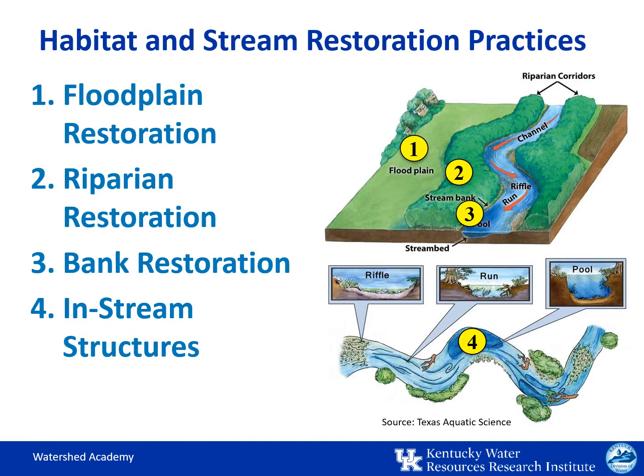Habitat enhancements frequently accompany stream restoration practices. Although individual habitat enhancements, such as boulder placement or felled trees, can be placed in the stream, the best approach to improve habitat is to restore a fully functional, well-vegetated stream corridor with a well-managed watershed.